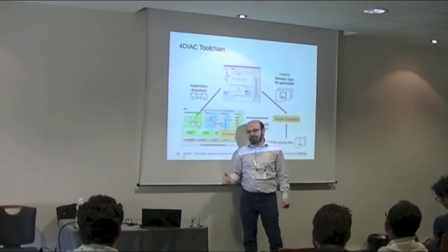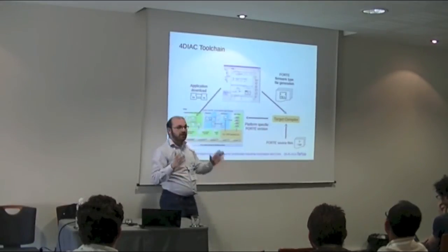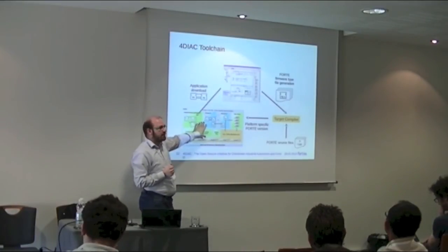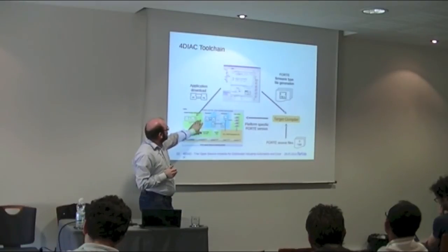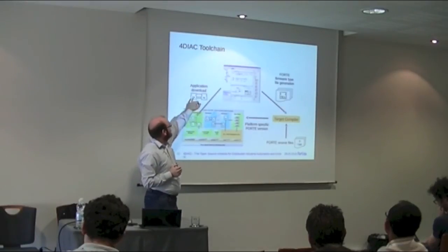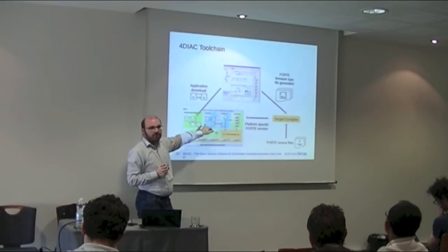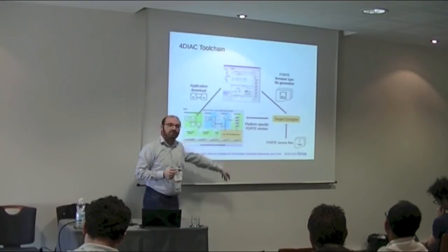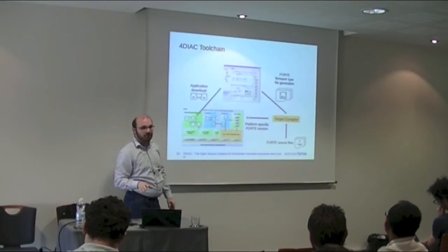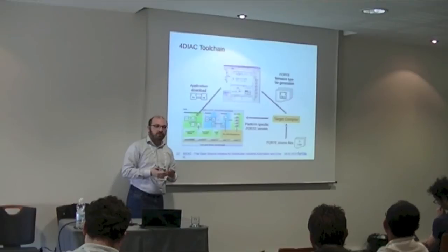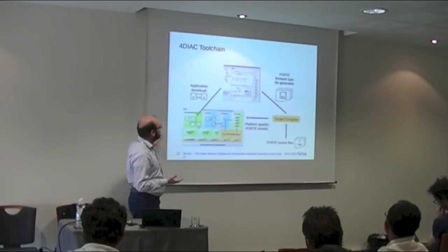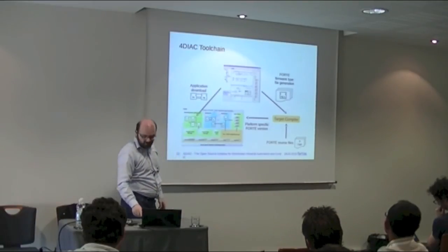So once you have developed your function block, you have tested your function blocks, you can build different kind of applications with it without changing the target device. And hopefully, and this is something we are investigating currently, how we would do it, we want to also download the function block types, so that you can develop a function block type, download it to your device, and independent what kind of device it is, it will run and execute the same. So this is also a point that we are targeting, making a platform-independent way of accessing all the different devices that are lurking around in industrial automation.